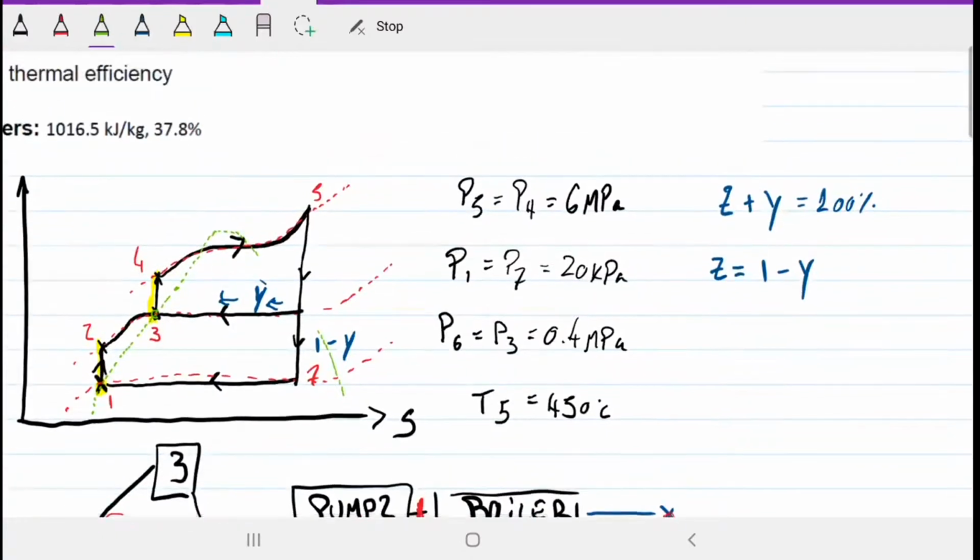So my dome is going to go something like this. Because we know these 2 guys here, 6 and 7, are both mixtures, they cannot be on the dome and they cannot be outside the dome, it has to be inside the dome. Okay, so now our TS diagram is correct. Messy, but correct. Let me actually get rid of some of these guys so it's less messy.